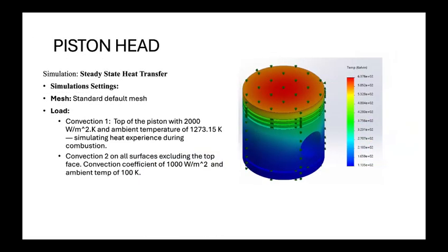We also ran steady state and transient thermal studies. The top of the piston was exposed to combustion level convection while the sides were cooled. The results showed that the max temperature was at 637 Kelvin with a minimum of 135 Kelvin.